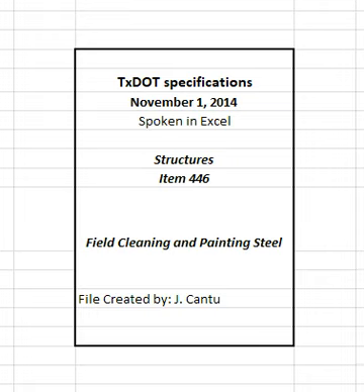3.1 Airless spray equipment. Use regulator and air or fluid pressure gauges. Use fluid hoses with at least 1/4 inches inside diameter, ID, and a maximum length of 75 feet. 3.2 Conventional spray equipment. Use independent fluid pressure and atomization pressure regulators and gauges. Use fluid and air hoses with at least 1/2 inches ID and a maximum length of 75 feet.